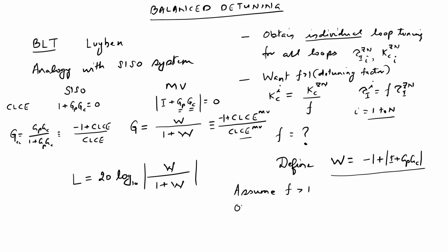Obtain L over a range of relevant frequencies, and then also obtain L max, the maximum log modulus, and I will put a CL there because it's closed loop.